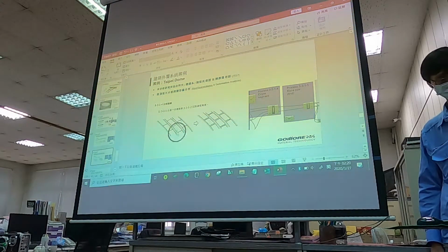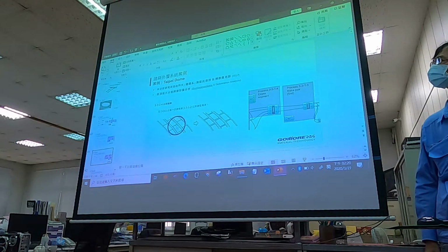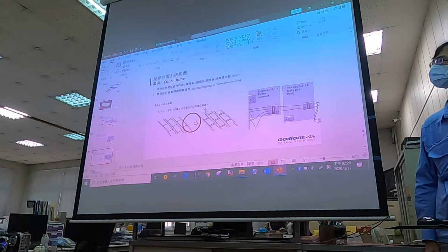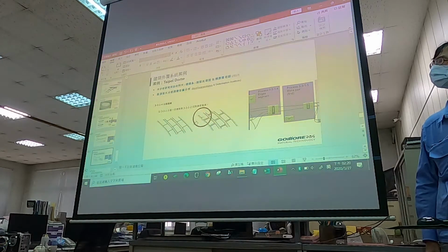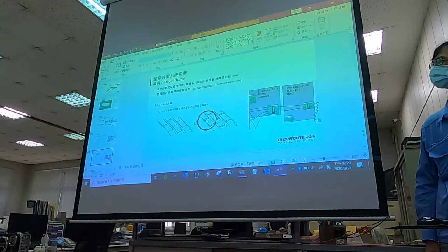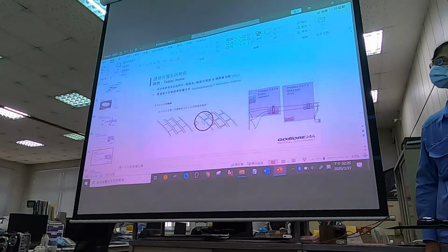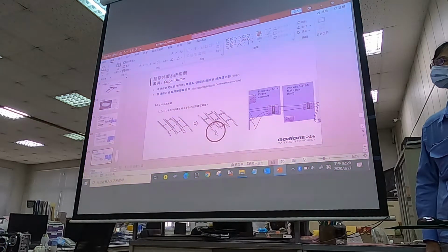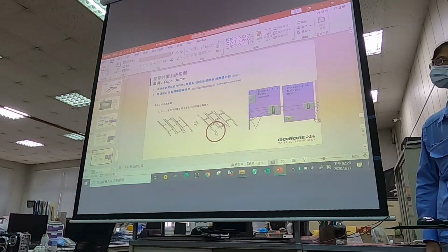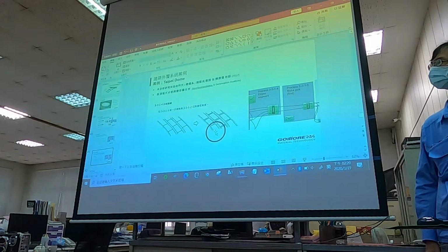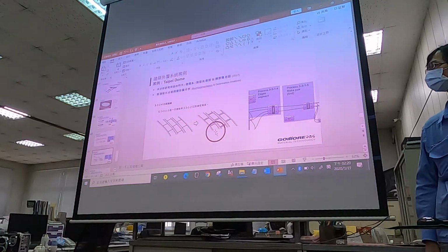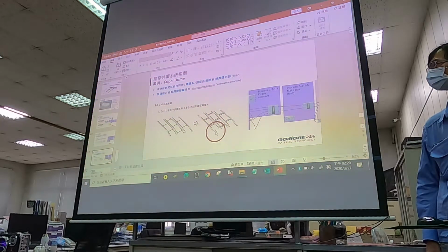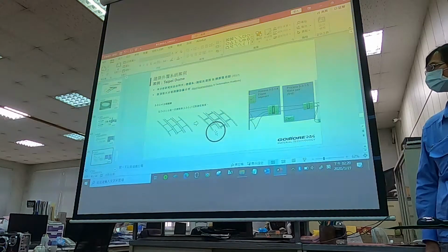When we have two panels butt joined together, they will squeeze each other. So we provide a gap between panel to panel. Then it is allowed that one edge might be longer than the other edge. So the intermediate space could absorb the difference of different edges. That's the trick that I use. No magic.